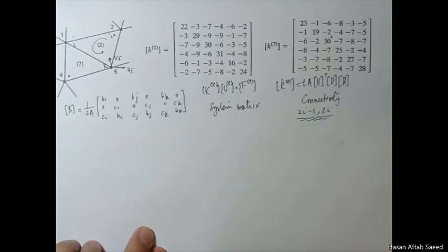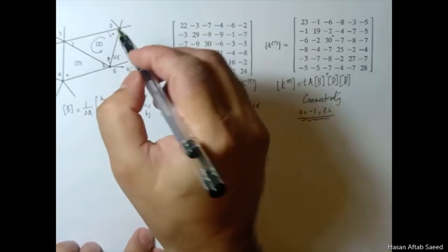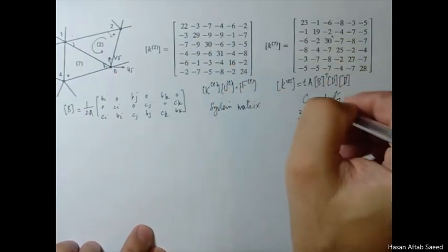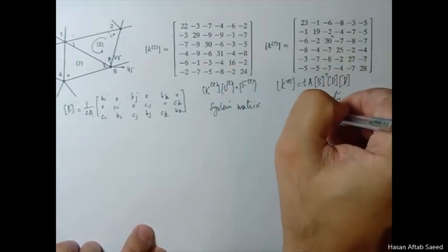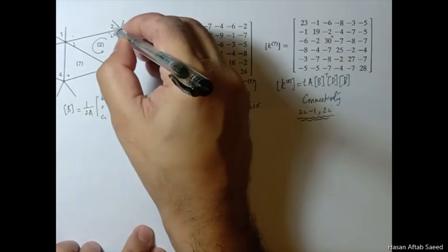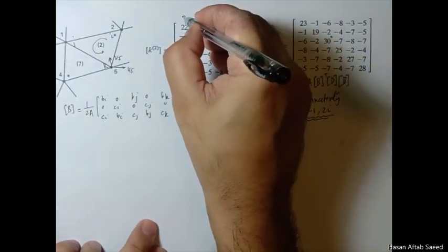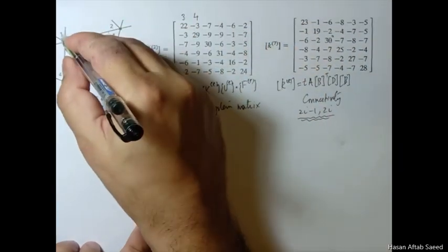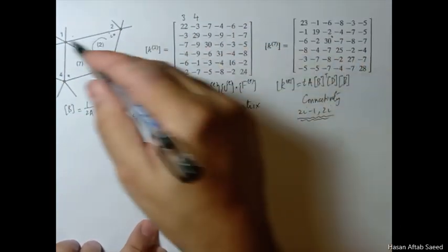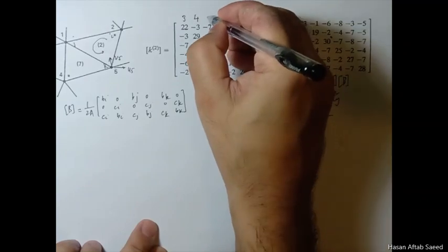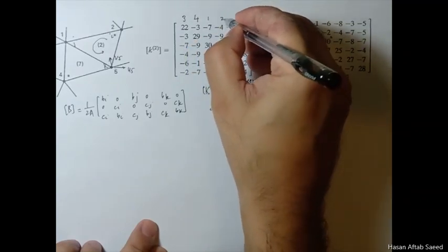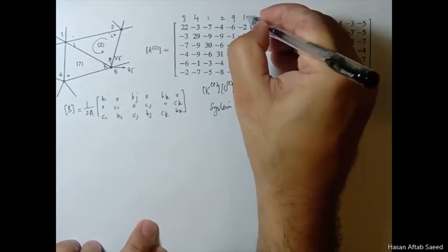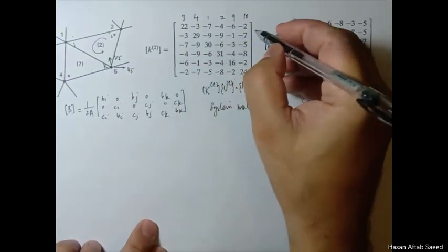Now if you do that, for node number 2, put 2 here, 2 into 2 is 4, 4 minus 1 is 3, so 3 and 4. So node 2 corresponds to degree of freedom 3 and degree of freedom 4. Similarly node 1, similar formula. You put the value of 1 here, so you get 1, 2. For 5, same formula, 9, 10. So you have this nicely specified.